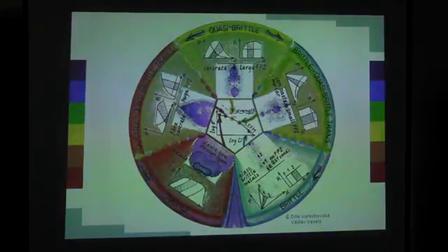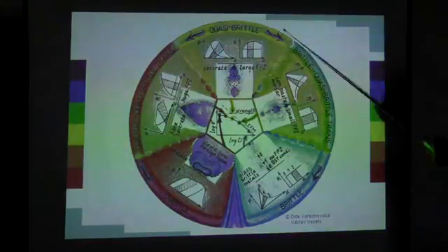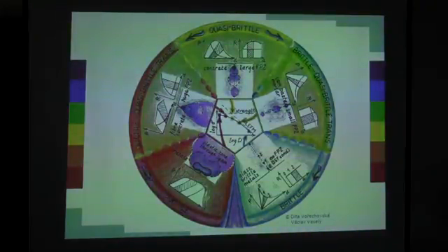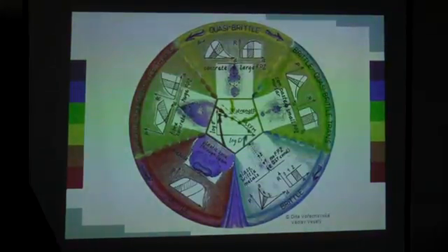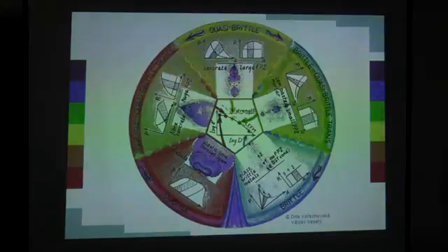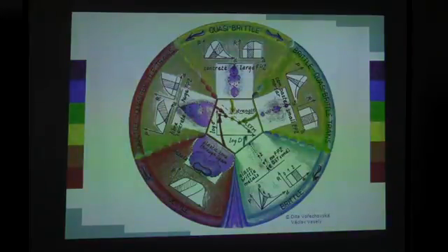So we are dealing with a concrete material with a very large process zone, and we can distinguish two entities within that fracture propagation. We can see the propagating crack and also the very large process zone, and the proportion of those two entities somehow describes the way, or the type, of fracture.